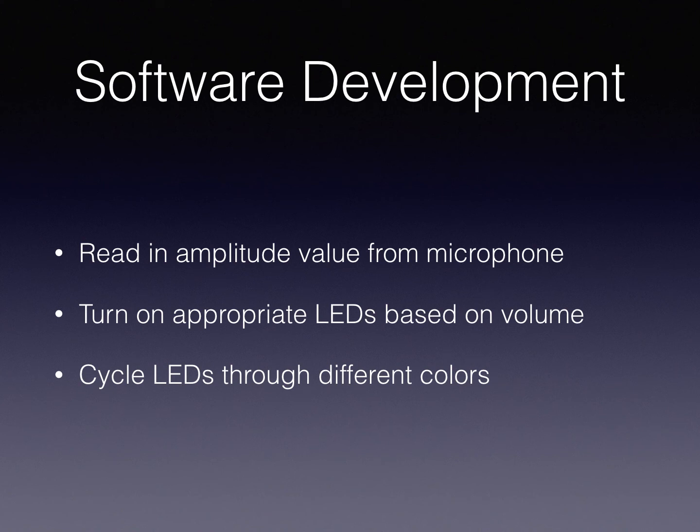And on that note, each iteration had a delay of 30 milliseconds, and so that was how I set a data rate of slightly over 33 hertz for the refresh rate of the LEDs and the microphone, which turned out to be great, as you'll see soon.